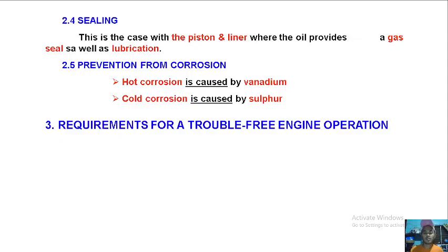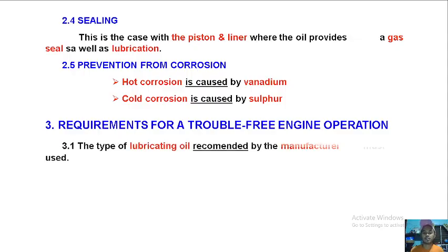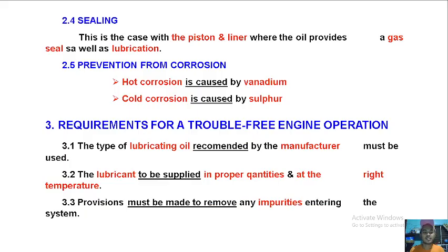What are the requirements for trouble-free engine operation? First, the type of lubricating oil recommended by the manufacturer must be used. Never use an oil that is not recommended by the manufacturer because it may cause damage to the engine. Next, the lubricant must be supplied in proper quantities and at the right temperature.